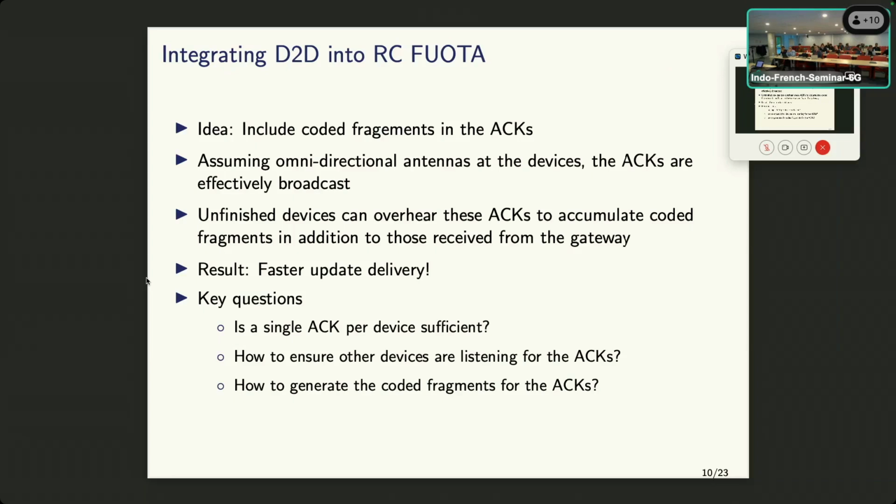And that is very important in this case because there are very strict duty cycle restrictions on LoRa transmissions because of their operation in the ISM band. In the European Union, it's 1%, which means that once the gateway transmits something, it has to wait for a very long time before it can transmit something else. So during this silent period, these acknowledgements will be transmitted.